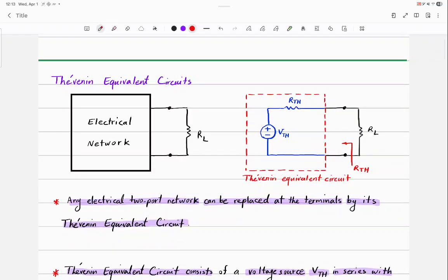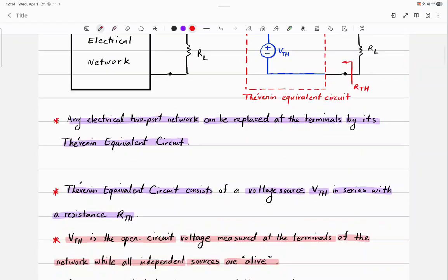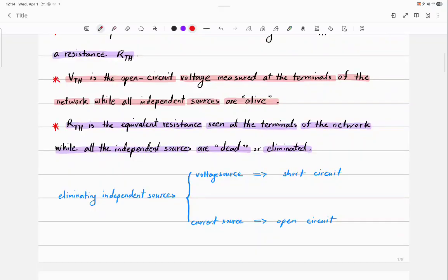Yes? So when we measure the resistance, is the RL there or is it open circuit? For measuring the resistance, no, RL shouldn't be there. And the reason for that is that if RL is there, then your multimeter will show R Thévenin in parallel with RL. And also, remember, RL is not part of your analysis or design or whatever. RL is the appliance that is going to receive your service, okay? For those of you who end up doing this job.